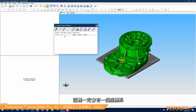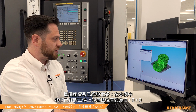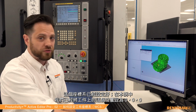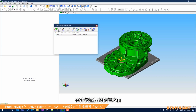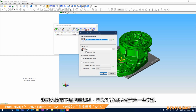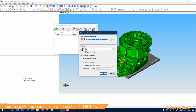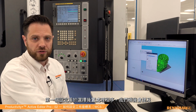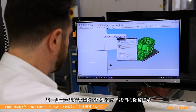We'll always have one coordinate system in here. There's always one that's set up, and at the moment we have that set to that location on our part at 000. Before we look at any of these buttons, I'm going to double click on that because there's some information here we might want to set. This very first setting allows us to choose our post processor. We'll come back to that in a minute.